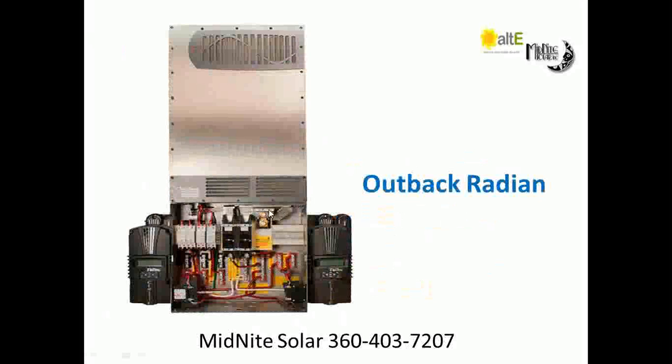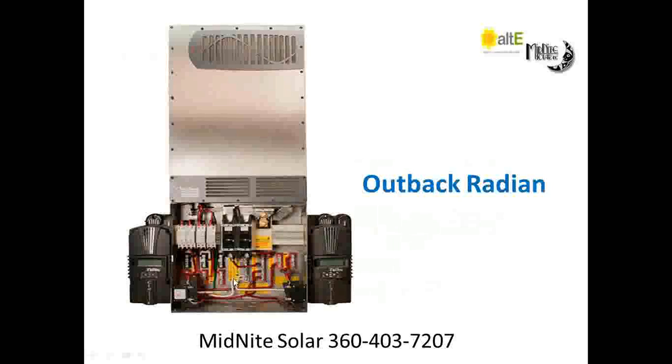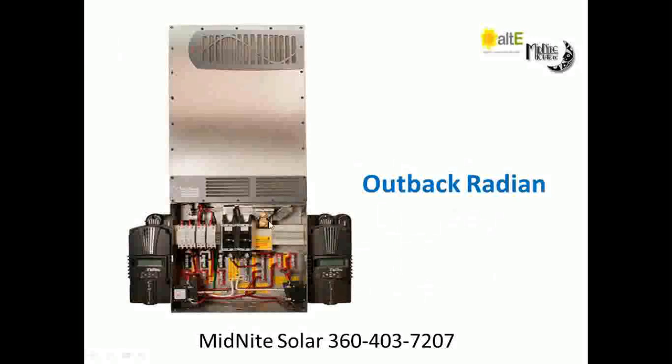And I point this out because this has thrown a little bit of a curve to a couple of people out there. They don't see the negative bus bar up here, and they see this white bus bar and end up hooking PV negative to that, and the charge controls don't work too well. So just something to point out, the DC negative is up here on the shunt on this one. Battery cables hook here, and then there's a positive combiner bar down here for one big battery cable.